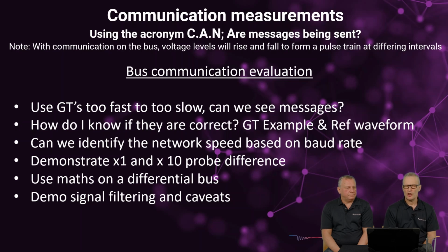Maybe not so much, we'll try both. We'll try CAN and we'll try FlexRay. We'll just see the influences your probe will have on your signal. We'll use what we call a math channel, and don't worry too much about that, because using our guided tests, these are already created for you. So you'll see, if we're measuring a 2-wire twisted pair differential bus, you'll actually see the differential value.